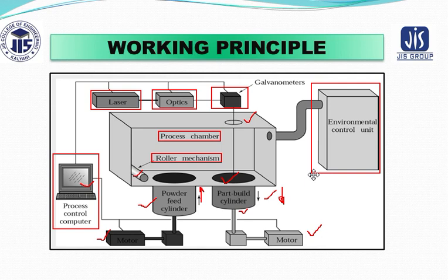So if you go with ceramic and metal, then it is very common to sinter only a polymer binder which has already been blended with the ceramic or metal powder, and then complete the sintering in a furnace. So hope you have understood the entire process of selective laser sintering from this particular figure. What you are doing is preferring the polymer for generating the product. You are basically using wax, metal and ceramics as the appropriate binders.